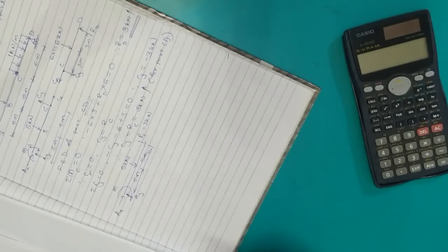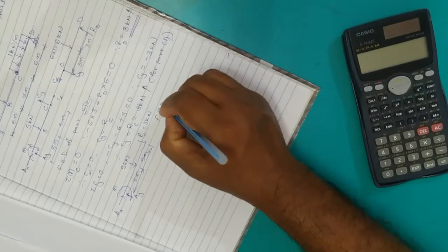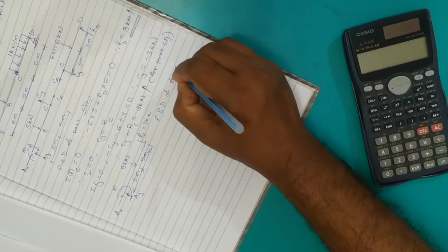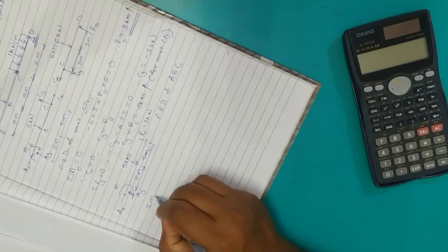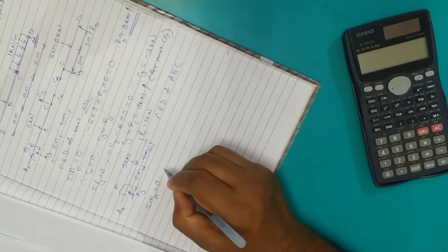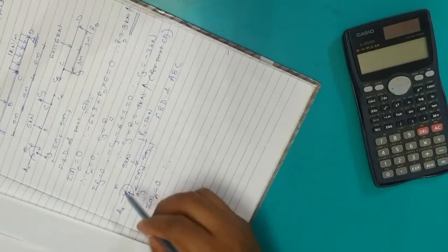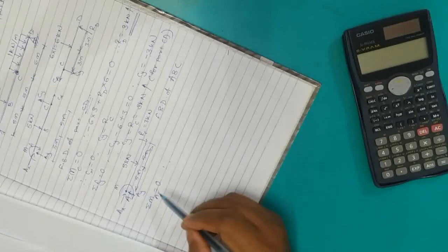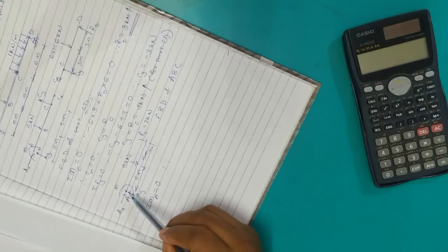Now we can solve this FBD easily. This was the FBD of part A, B, C. So now let's apply the condition of moment, let's say about point A. Now here we know that if forces are applied at the fixed point, and here A is our fixed point about which we are going to calculate the moment, the moment is 0. Whatever forces are applied on the fixed point will have 0 moment.